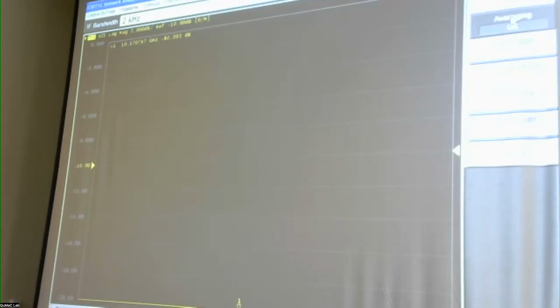If you remember in that diagram, there are all these crosses inside a circle. Those are actually the frequency converting devices, the mixers. So the bandwidth here refers to the mixed down signal, because that is actually what is giving you the scattering wave amplitude. So it's a low frequency amplitude of that mixed down signal, so it's called IF. Such a nomenclature.